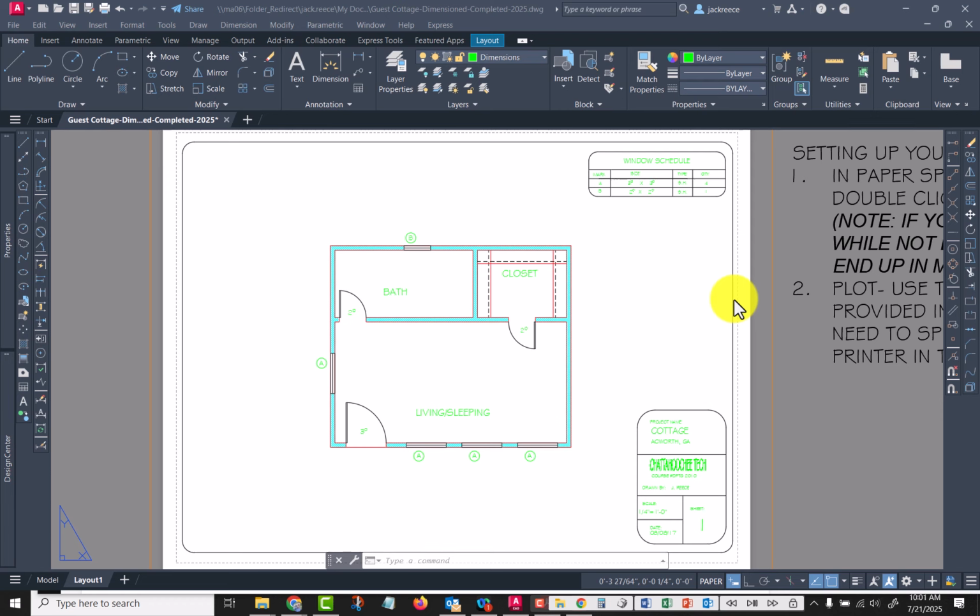I hate to say it's an old method of AutoCAD dimensioning for architectural stuff, in that you make all your settings for what size you want your text to be, your arrowheads to be, things like that. And then you apply a scale to the dim style, and it will scale all of that up. In the textbook, they use a scale of 48. In their videos, they use a scale of 24.